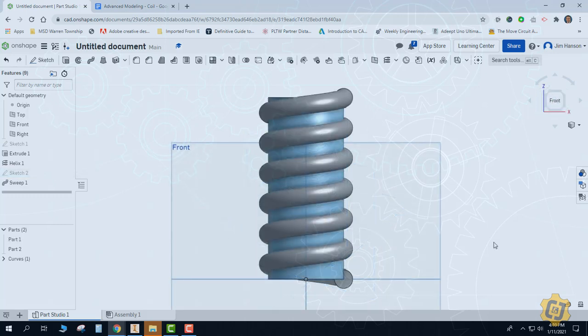So the first thing I really want you to notice is that blue cylinder is actually part inside my coil. That's unfortunately because that's the way I drew my coil. When I drew that circle, I locked it onto that bottom corner, so now my coil is kind of half on, half off that blue cylinder. If I actually wanted that blue cylinder to be the core, or the total inside, then my circle would need to be off to the side a little bit. Let me show you.